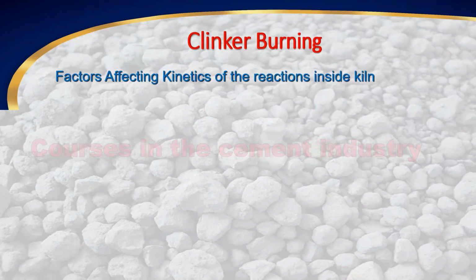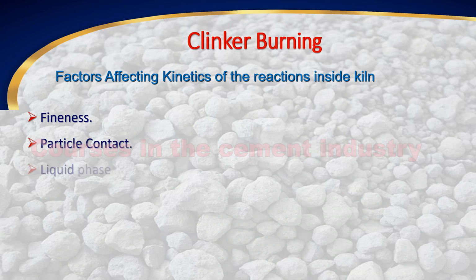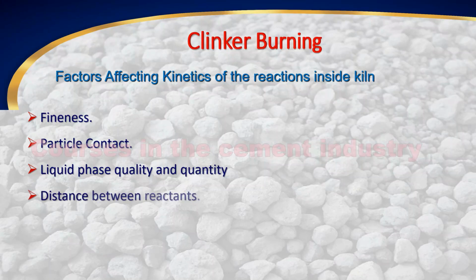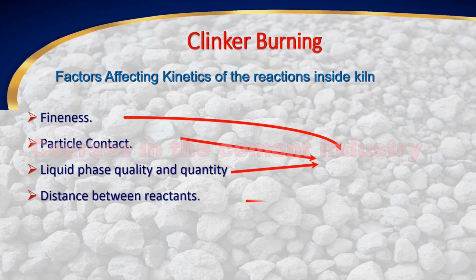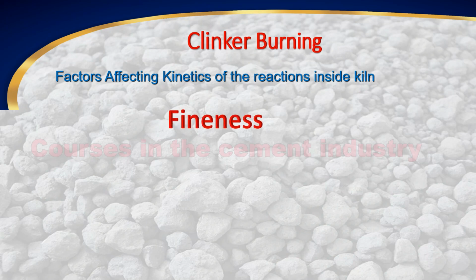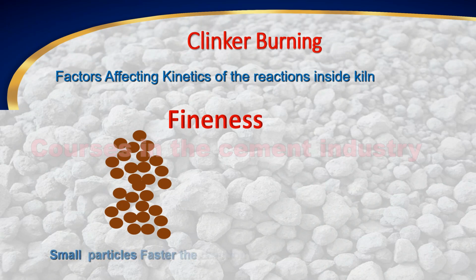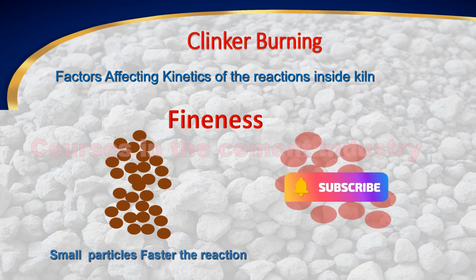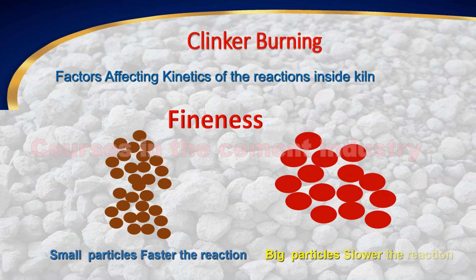Factors affecting kinetics of the reactions inside the kiln. 1. Fineness. 2. Particle contact. 3. Liquid phase quality and quantity. 4. Distance between reactants. All of these factors fall into kinetics. Fineness: in this diagram, the smaller the particles, the faster the reaction; the bigger the particles, the slower the reaction.